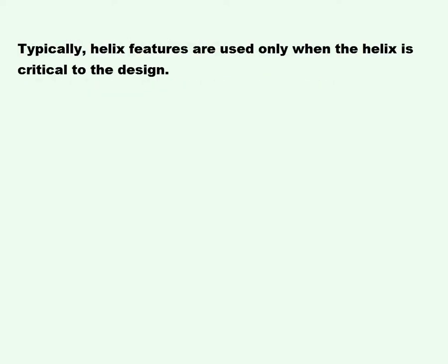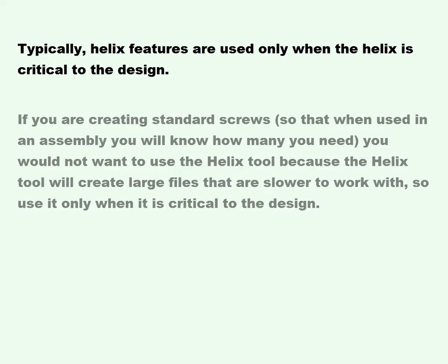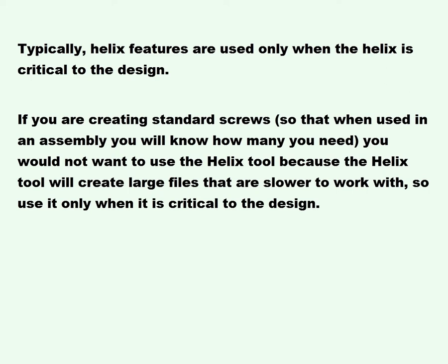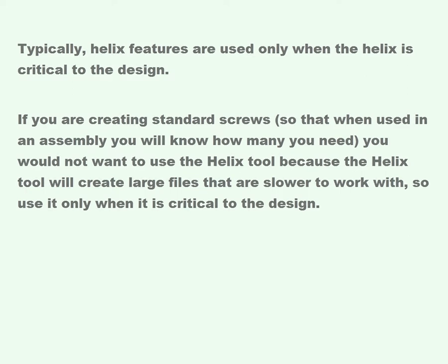Typically, helix features are used only when the helix is critical to the design. If you are creating standard screws so that when used in an assembly you will know how many you need, you would not want to use the Helix tool because the Helix tool will create large files that are slower to work with, so use it only when it is critical to the design.